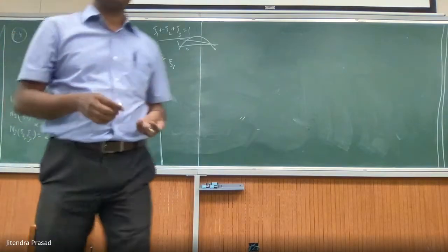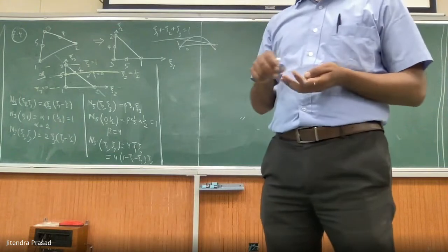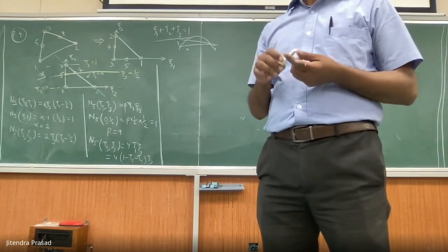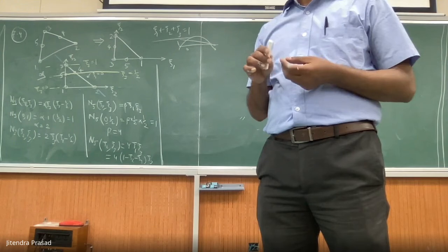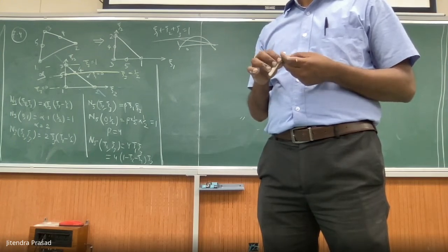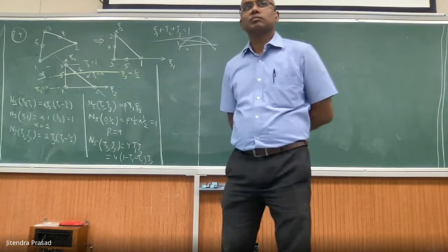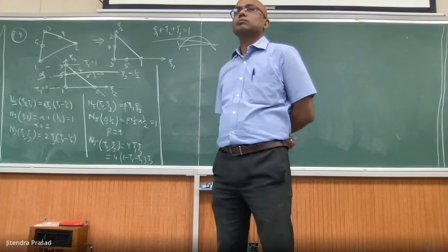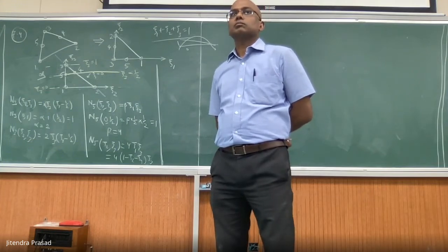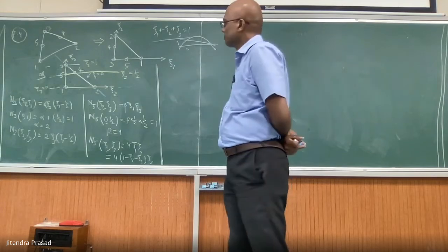I was saying that for any point in between in the element, we write the summation of N_i times the nodal values. For the equation to be linear on 1, 2, we just have to prove that N1 and N2 are linear, because the rest of the shape functions N3, 4, 5 will be 0 on the line 1, 2. So as long as N1 and N2 are linear, that will give us the answer, right?